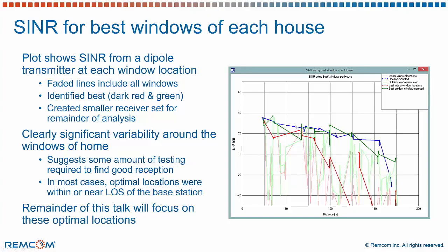So what we could see here is that the rooftops perform pretty well. We didn't have to take the best of those. They were just in a fairly optimal position on the roof. It's easy for the signal to propagate to those positions. So the dark blue line does pretty well and gets a fairly high signal to noise even without any of the beamforming. We're achieving as high as high teens or 20 dB signal to noise ratio. The exterior window mount does fairly well as well. But if we look at the red values, we can see that the interior windows drop off very quickly.